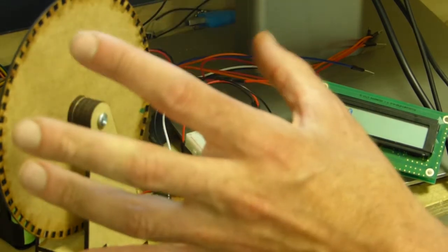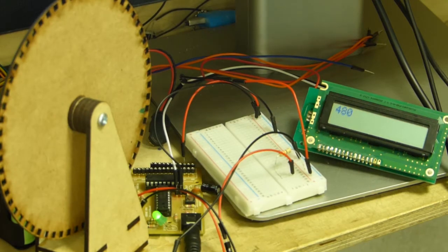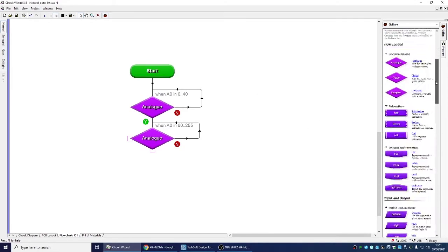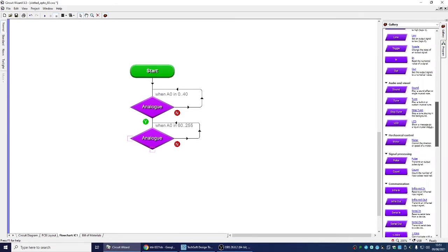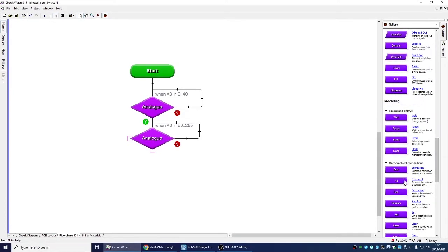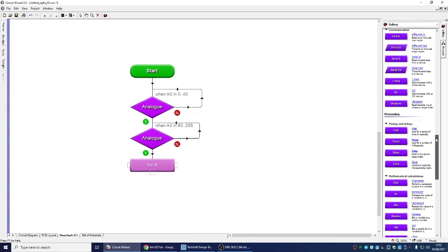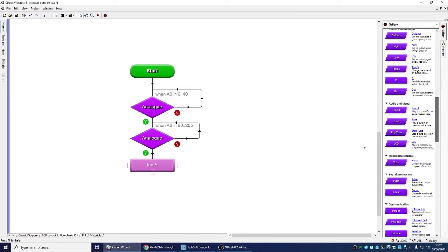Then as soon as you move it and it goes dark, yes. Now is it light again? Has it moved again? So what you're looking for is it having been dark and then light. If you go through both of those states, then we're going to take a variable here. Let's find this one here, increment. I'm going to start with something called variable A, and I'm going to add 1 to that amount. Once I've done that, I'm going to plot on the LCD what that variable is.